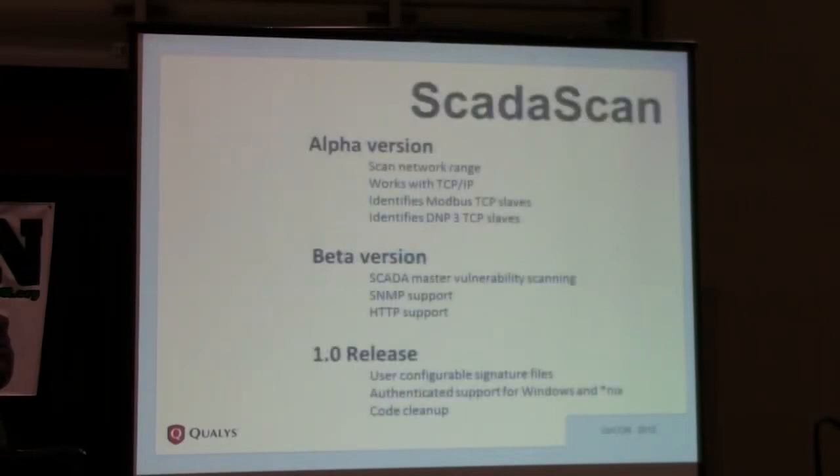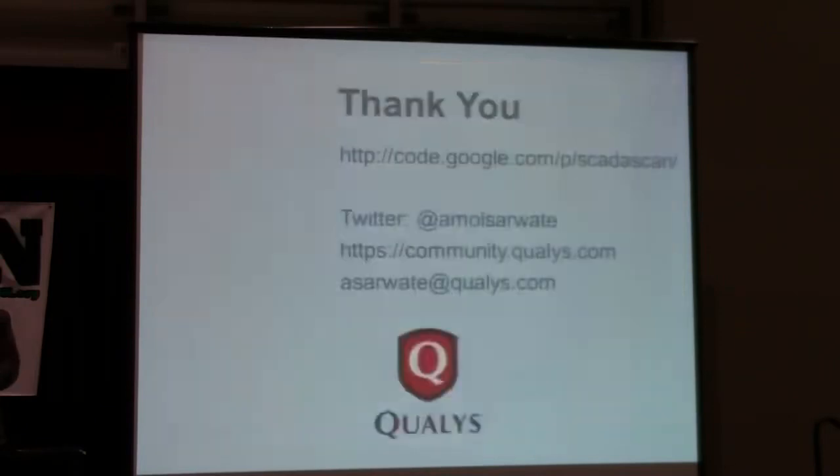This is a little bit of a roadmap of the SCADA Scan tool, which is currently in the alpha version. It supports Modbus and DNP3. In the beta version, I plan to add some SCADA master vulnerabilities, and support for HTTP and SNMP. But in the final 1.0 version, what I really want is user-configurable signatures, because the fact is that no company, my company or any other, will ever be able to get their hands on all types of SCADA systems. So if it's a community-based thing where you could upload your own signatures to the tool, that would be fantastic, and that's the goal of the tool.